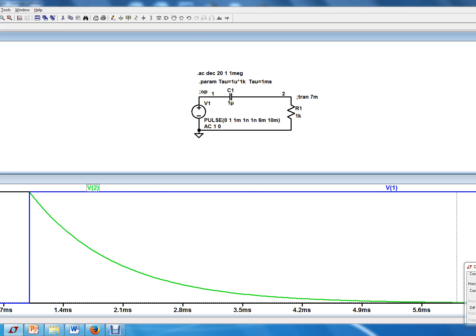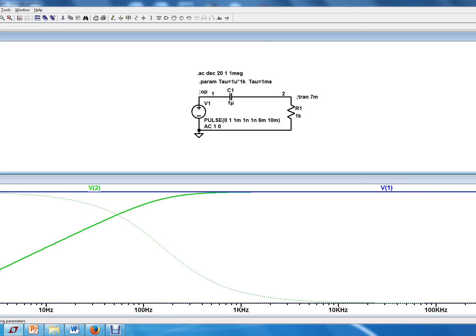So now all we have to do is run, and we see not a step response of a low-pass filter, because notice this scales in dB, and this is in frequency, not time. But see, V1 at every frequency is at 0 dB, which is 20 times the base 10 log of 1, which is 0 dB. And we can see that V2 is attenuated quite a bit near DC. 1 hertz is still 1 time a second, but that's getting pretty close to a DC signal.